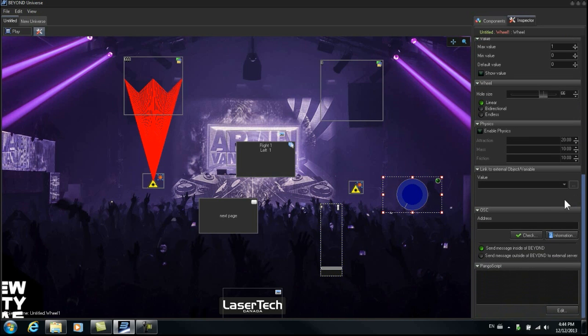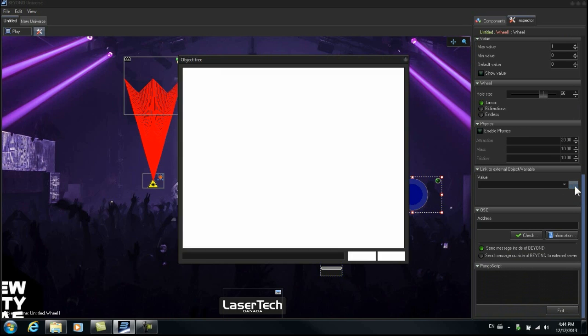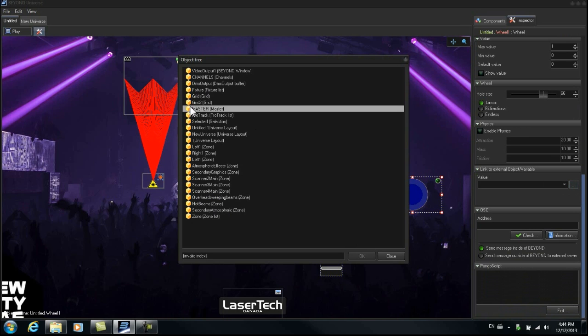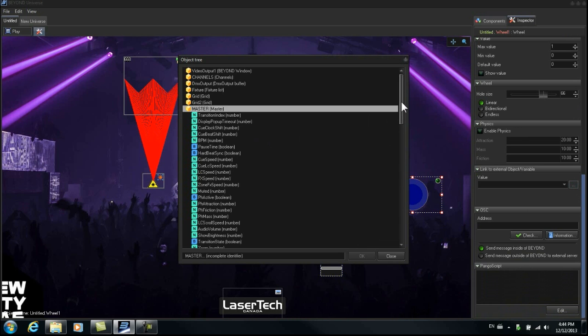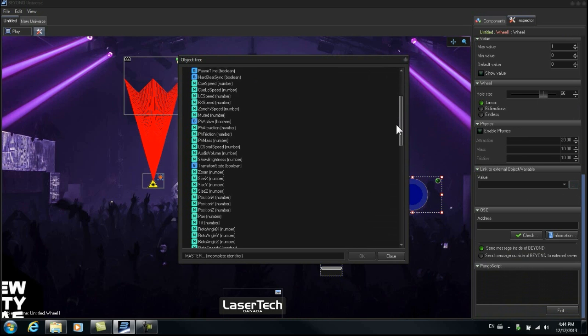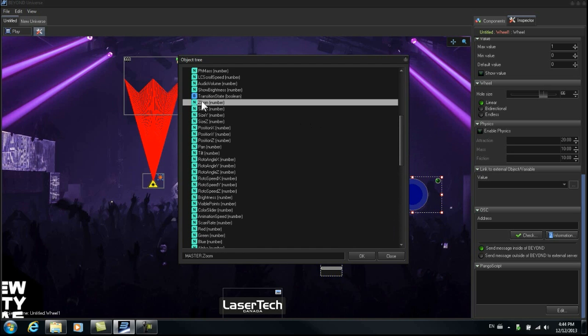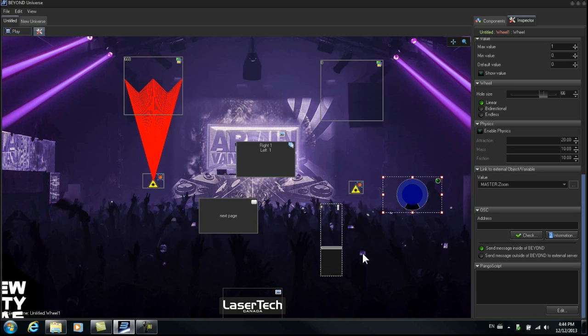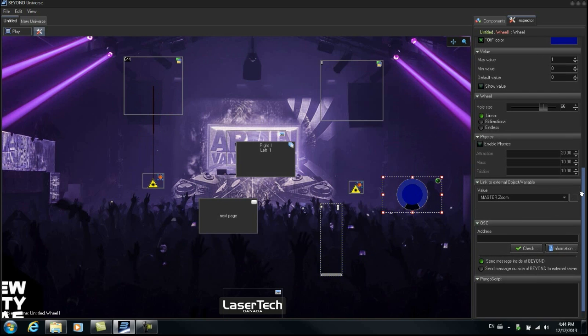We're going to link this to master zoom. So let's search. We can go right to master. And find our zoom. Here it is. Zoom. We'll double click on that. The command is quite simple. It's master.zoom. So now we've linked this wheel to the master zoom.